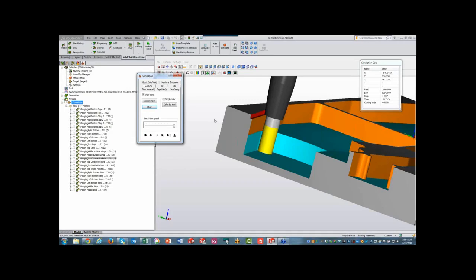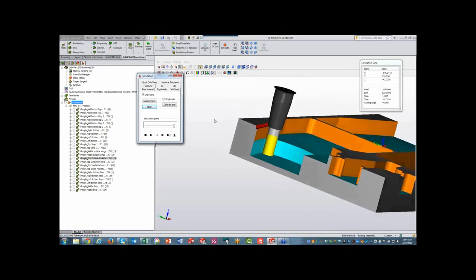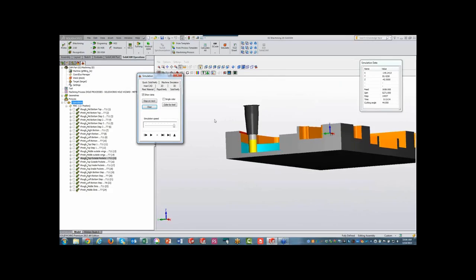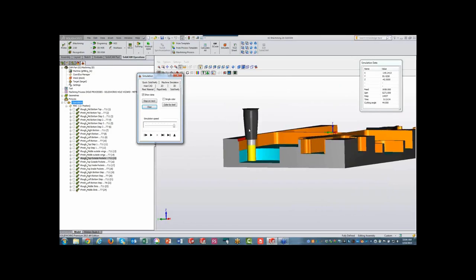This is a major point between iMachining 2D and 3D as well. There is no protection from holders in iMachining 2D. I have to take that into account. I have to know about this beforehand. Maybe have my tool go up, my holder go higher, if I can. If not, then I have to use two separate tools. All this I have to take into account.